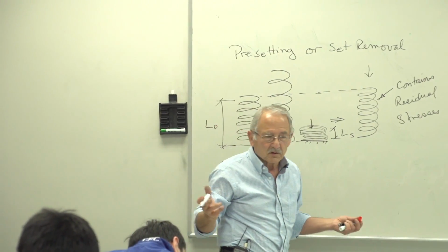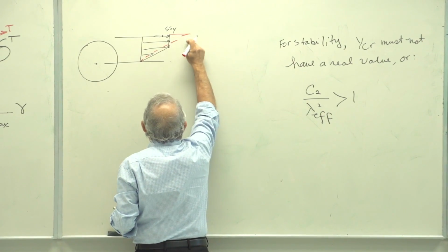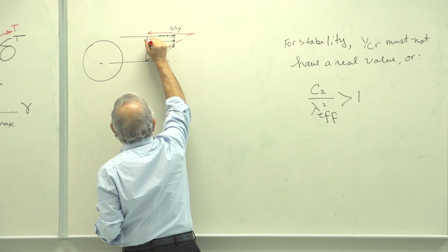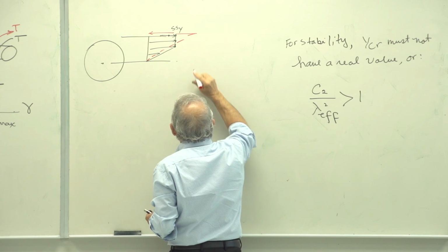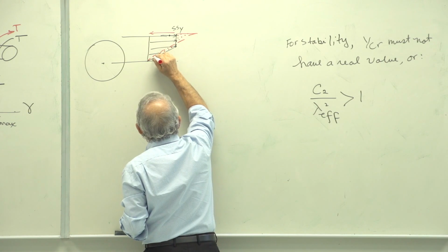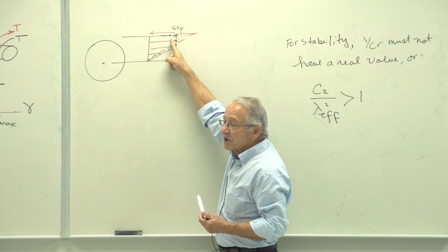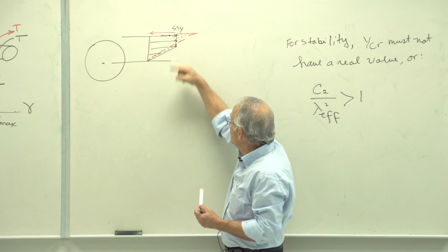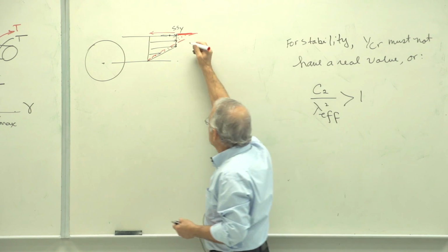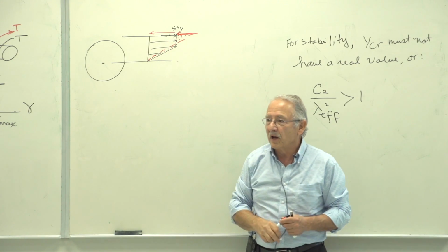So somebody asks, what are residual stresses? You can say you know something about them. So the difference between these two stresses, and this red stress is in the other direction, by the way. It's in this direction. I don't want to draw the rest of it. The difference between the two is this. And notice that the red stress is larger than the black stress. So the net residual stress, this is the net residual stress here, is in this direction, which is in the opposite direction of the originally applied load.